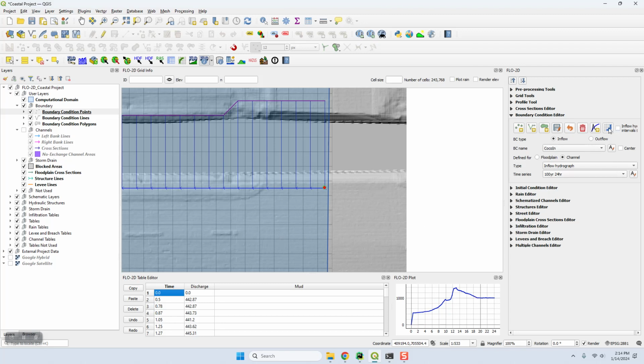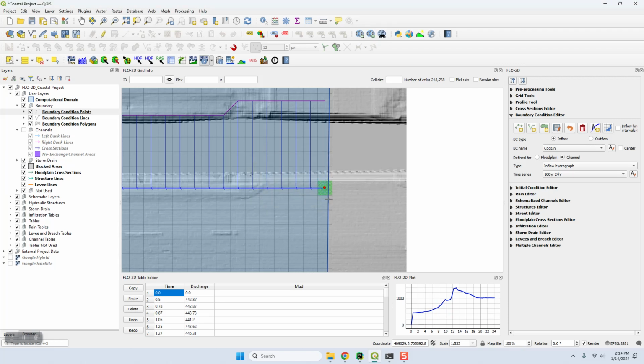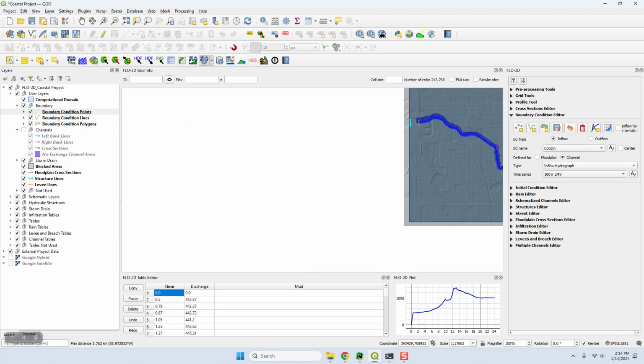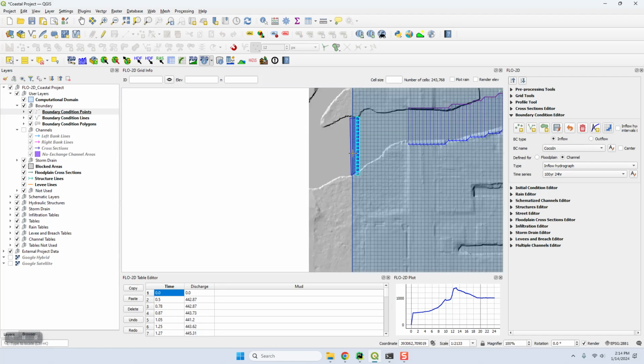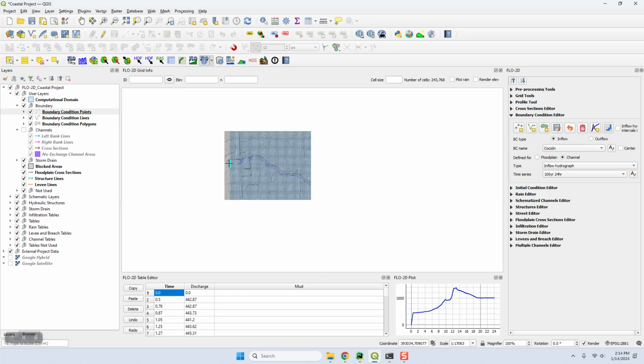So now all we have to do is click the schematize, and we're just going to overwrite the data that's in the system. Click yes. And what you'll see is that you have one inflow node, and we already did this in the boundary lesson, like 32 outflow nodes. Now, and I may have discussed this in the boundary video, but these ones on the outside set the tidal stage, and these ones on the inside allow the water that is in excess of the tide to leave the system at like a normal depth discharge relationship.